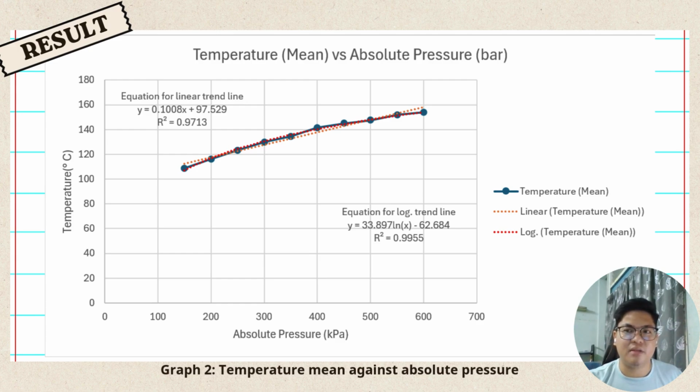From the graph we can see the behavior of the pressure and temperature is non-linear, and the R square value represents that the closer the value to one, the better it matches the data trend. So in this experiment, we will use the equation of this trend to compare with the theory, the Clapeyron equation, to see the behavior of the water in two phases, steam and liquid, and we will see the pattern of this experiment.